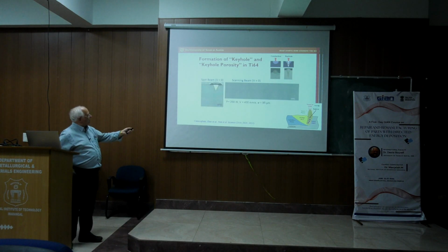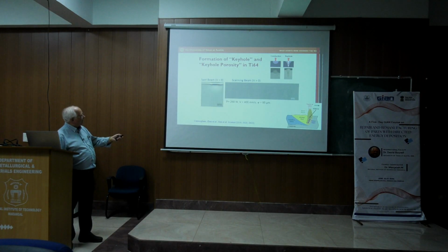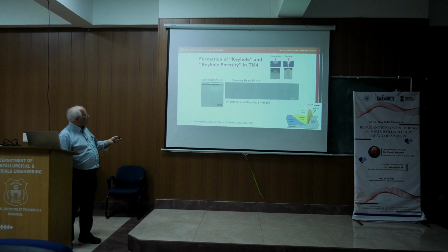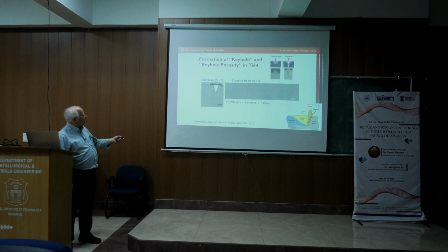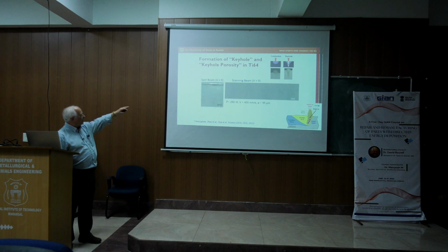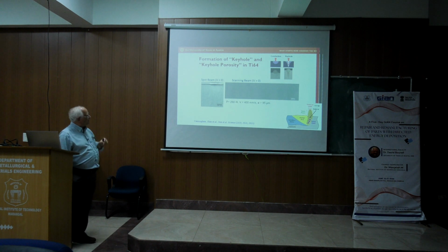So you can see the laser coming in, and the white part is actually molten metal. Hopefully it'll run again here. So there's the laser, it comes down and creates that melt pool, and then when the laser goes off, you see there's some rebounding of the melt pool, and it makes a melt that solidifies.